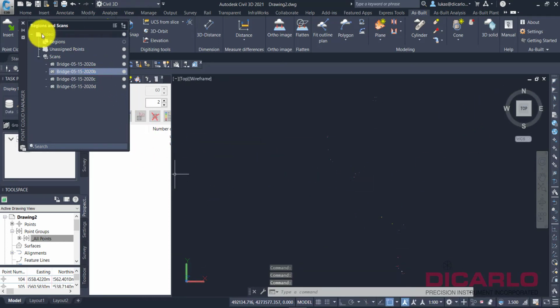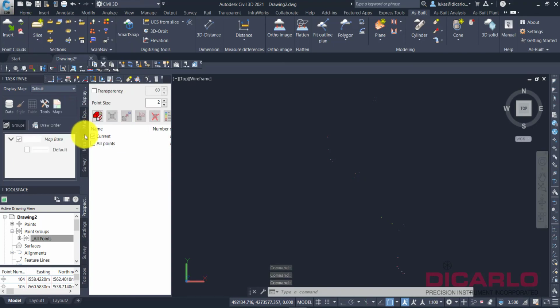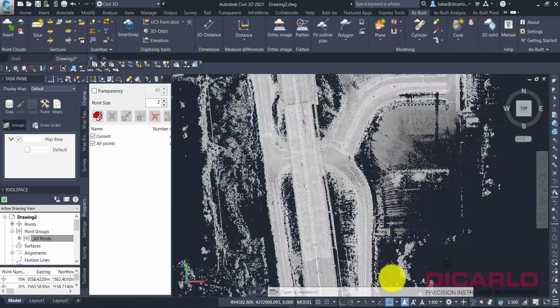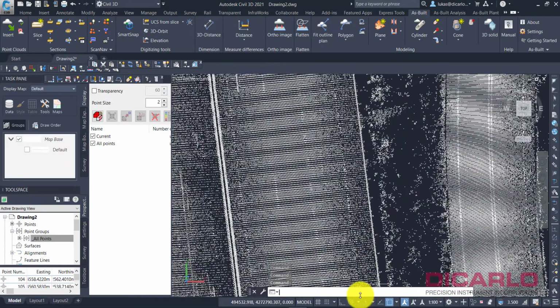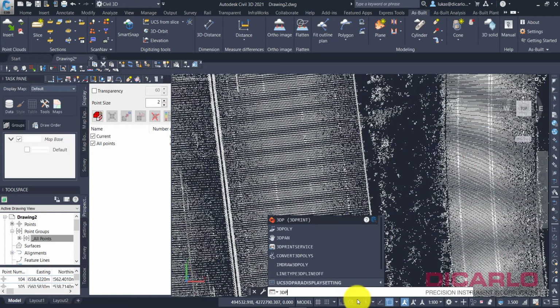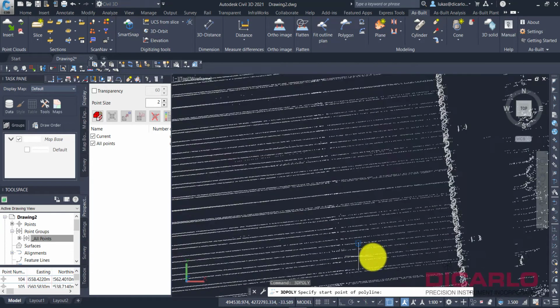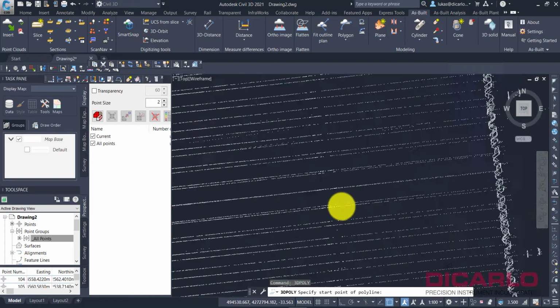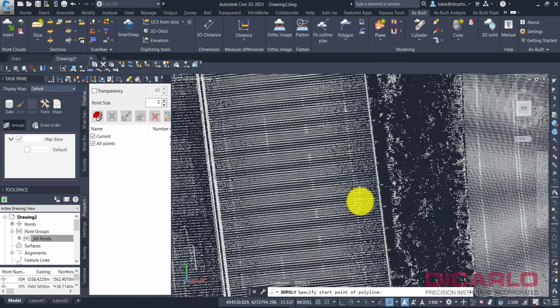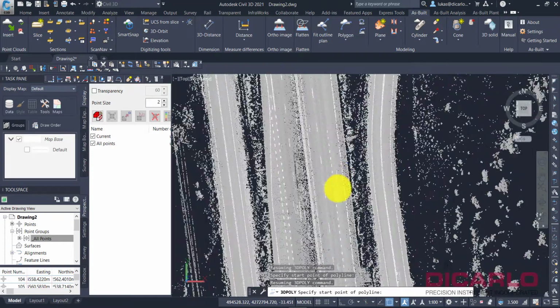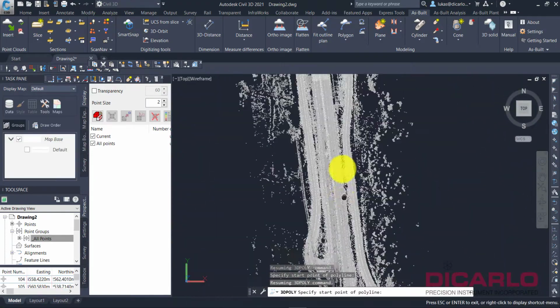When you have large coordinate transformations, the snapping feature, when you want to draw something, let's say a 3D polyline, you'll notice that instead of going right below the crosshairs, it goes above or at different zoom levels elsewhere. That's really just a result of having a really large coordinate transformation.